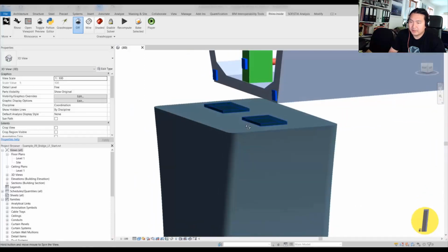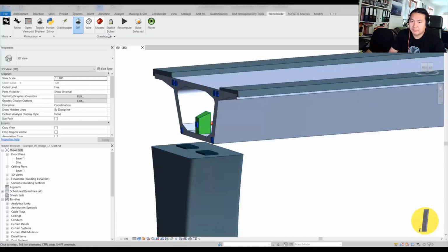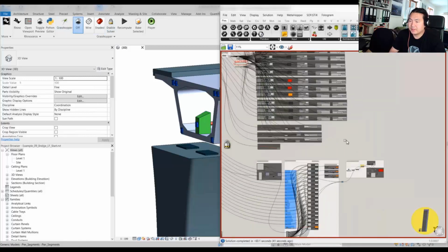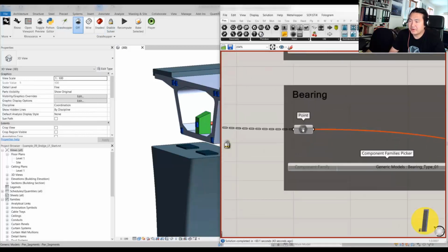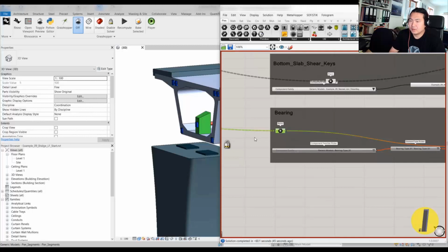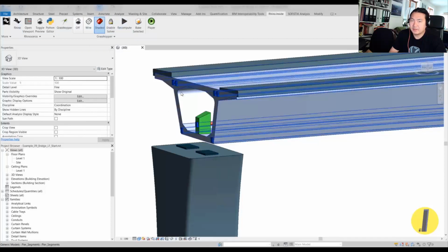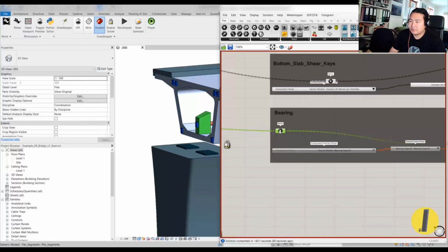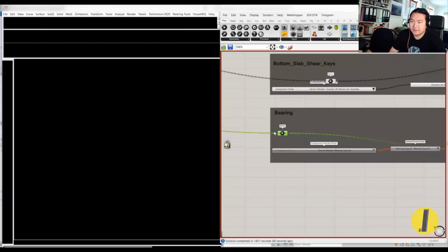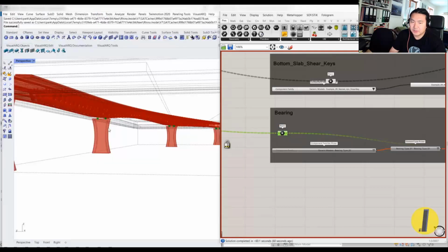And as you can see, I'm going to also apply another loaded family, which we just built as a Revit family. So if I go now, insert bearings, we will find every point of the bearing location from the Grasshopper script. And at this point, we can insert the specific Revit family. So I'm going to open Rhino to verify once more the bearing position.